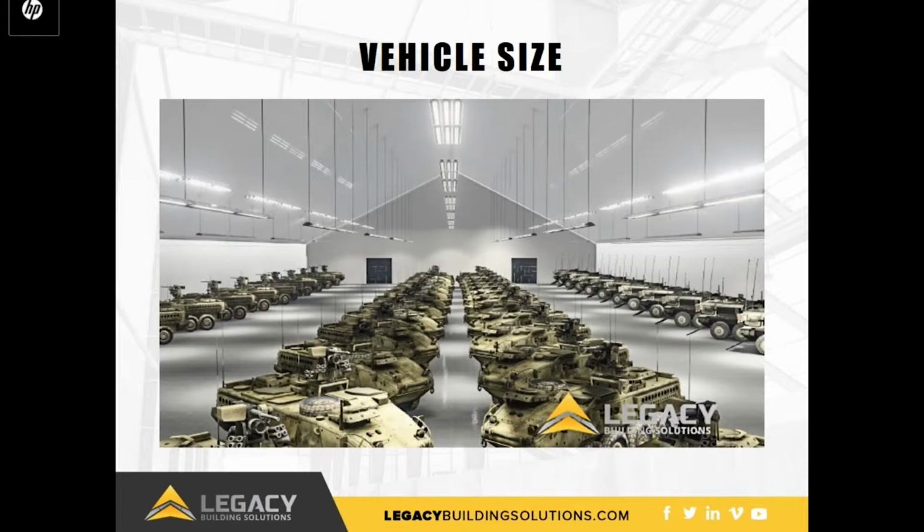These buildings are often used for hangars or truck shops. The building designer should be able to create a rendering showing the exact dimensions of your vehicle and how it will fit into the building. Using these scale drawings will give project stakeholders the chance to consider how anything else in the building will interact with the vehicle. For example, you will need another door for personnel to enter safely, and where will it be placed? Will there be room for a bridge crane or a tipping truck moving around in the building? These considerations will help avoid disaster.